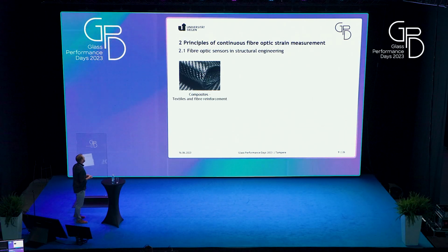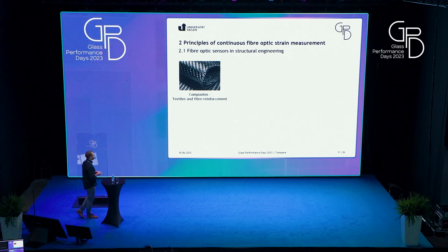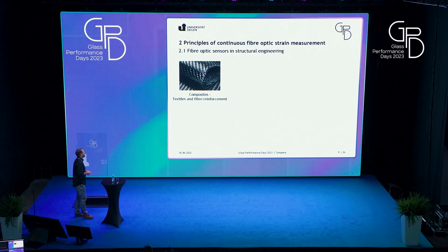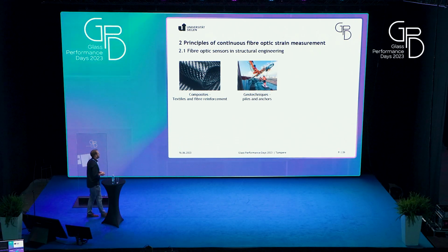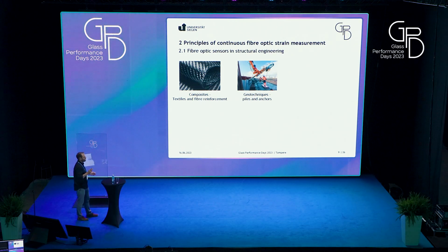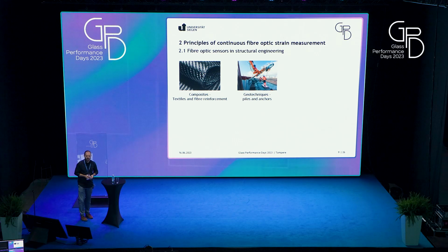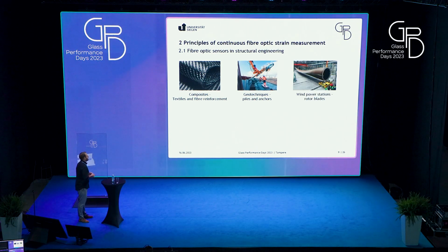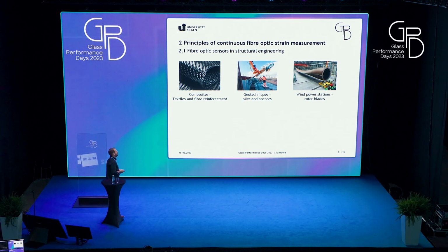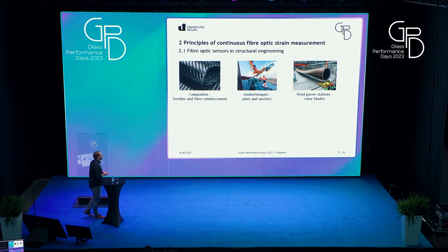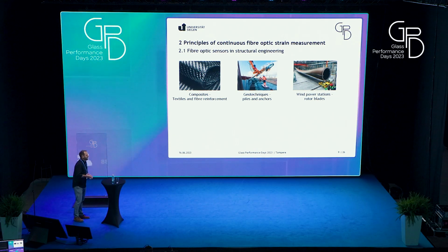And some examples where fiber optic sensors are applied in structural engineering. On the left picture we see textile. The next one is from civil engineering, geotechnics, piles and anchors. The fibers are embedded in a concrete anchor so that you can monitor it over long-term experiments. And another example given on the right, a rotor blade from a wind power station. It is laminated too.